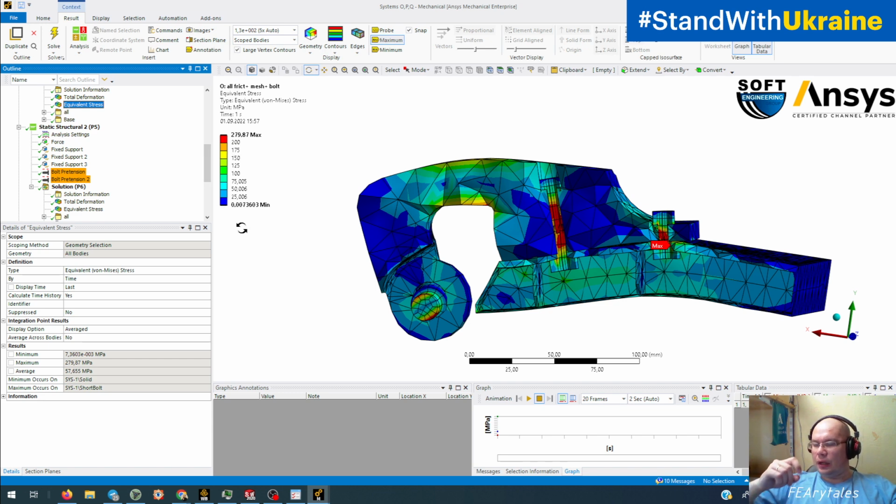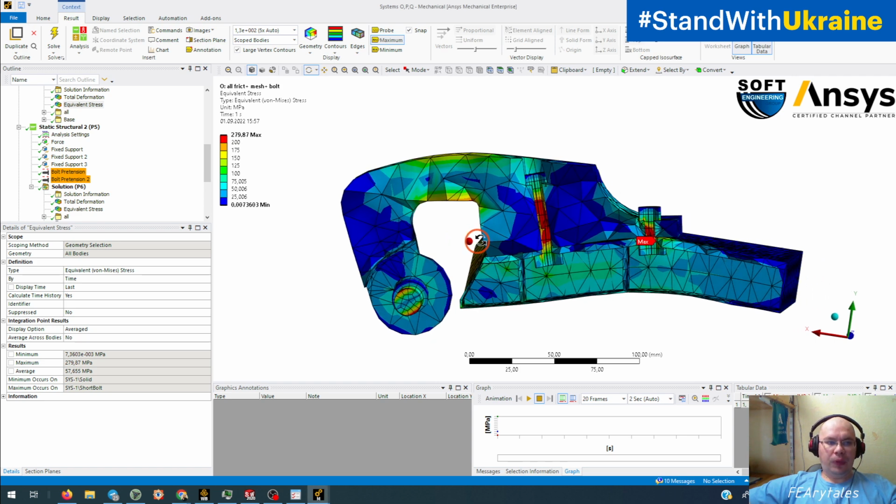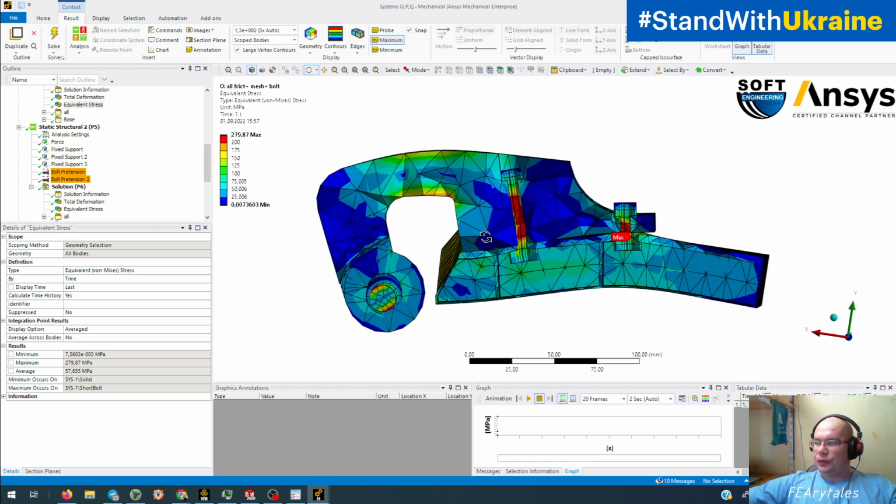because stress is a more accurate result. It's more sensitive. So why do we have a difference? We have a linear material model and it doesn't matter, but we have a nonlinear solution. Contacts give us nonlinearities, and we came through two different ways.